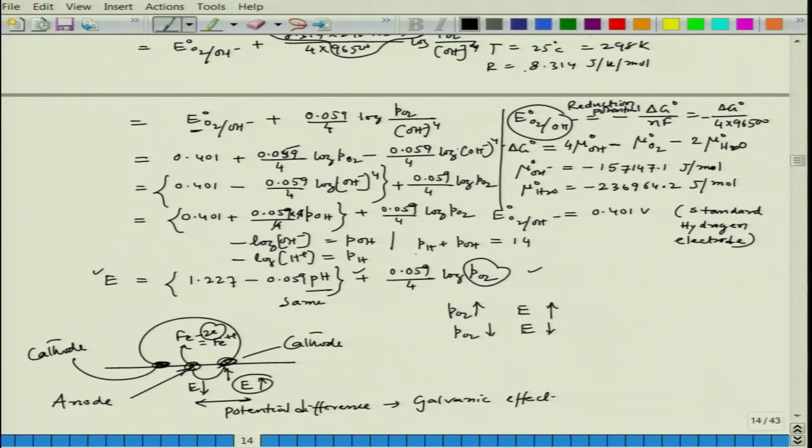And why is this coming up? Because of oxygen depletion and the difficulty of oxygen getting from the top surface to the center of the droplet. Okay? So that is how this difference arises. Initially it happens uniformly, but later the corrosion will be concentrated at the central location. So it started in a uniform mode, but gradually it goes into the center part. So it is a localized mode, and this is happening because of the galvanic effect, which is coming due to the concentration difference.